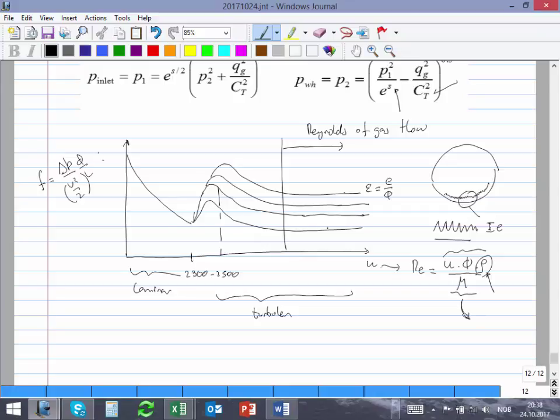It's just a constant with Reynolds number. It doesn't have any dependence. It only depends on the relative roughness. If I have the relative roughness, I already know the value of the friction factor. Clear so far? So I take away all what we have to do for liquid, where we read the Reynolds number, go to the Moody or the Colebrook graph, and then read the F. I take all of that away from my mind, because gas is always very, very turbulent. I don't have any dependence on the Reynolds number. Sounds very crazy, but that's the beauty of gas.